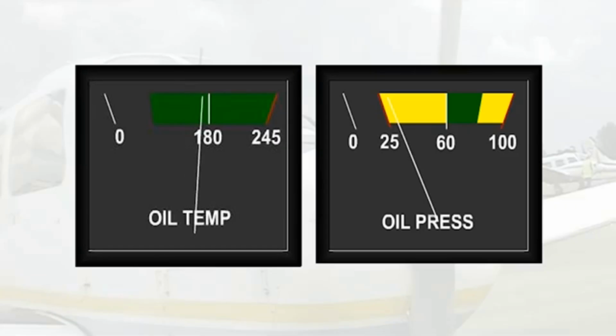If the oil pressure is too low with associated high oil temperature, then this is probably due to the temperature causing the viscosity of the oil to drop below the point where the oil pressure relief valve can cope. If the engine is fitted with oil cooler shutters, then they can be opened in an attempt to lower the oil temperature.